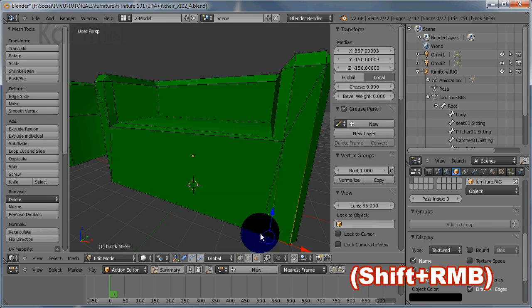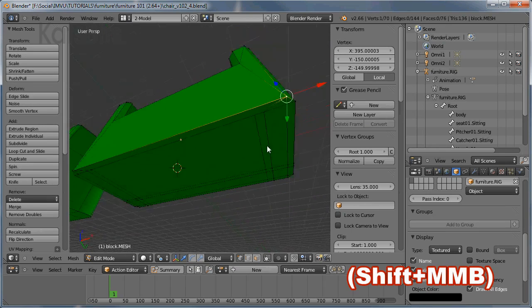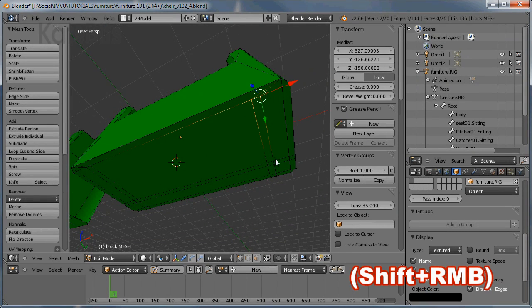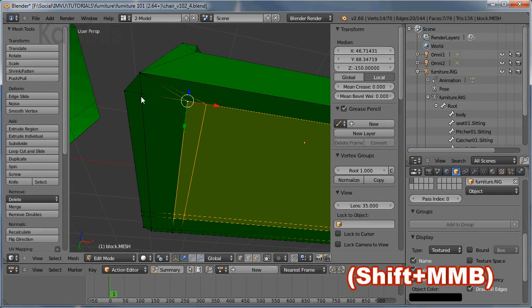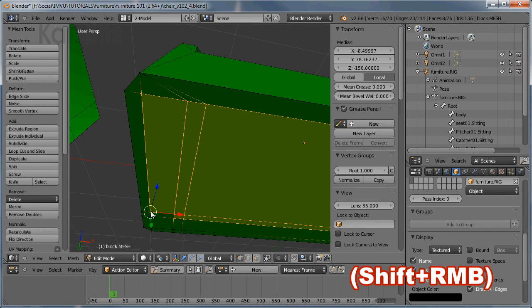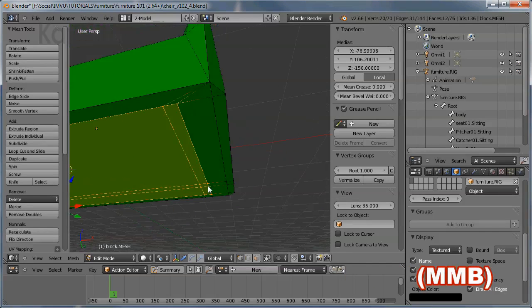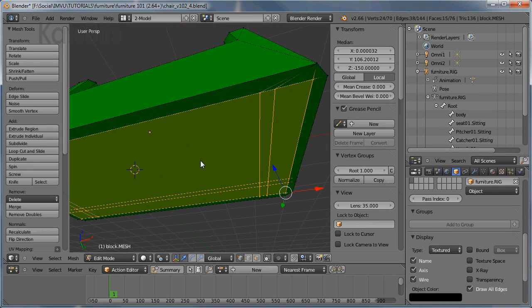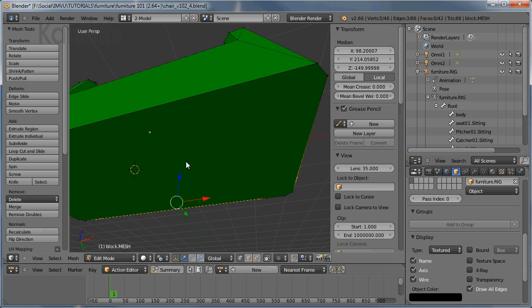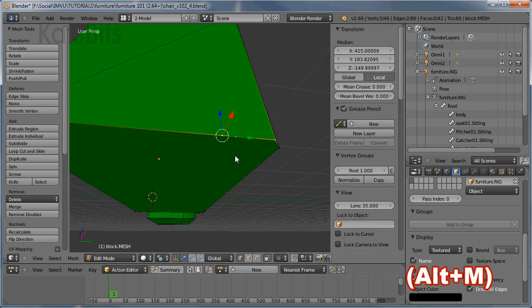And we should find that the underside of the mesh still has, yes it does, so select all of these vertices, taking care not to select the vertexes that are along the outside edge. And use X, Limited Dissolve. That will leave us with the odd stray vertex, which again needs to be removed.